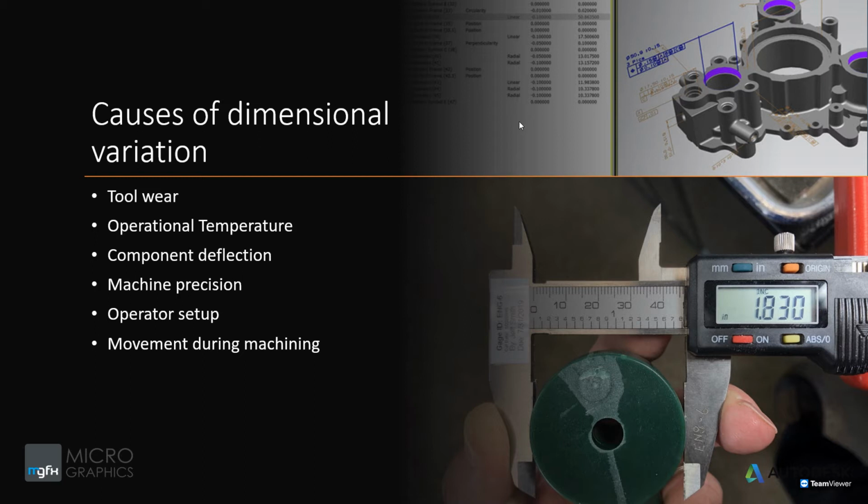Like I just spoke about earlier, we know that different manufacturing processes have various sorts of tolerance values. That depends solely on the nature of how a part is made. So for example, machining might be a little more accurate. You're working with 0.1, 0.005 tolerances, depending on the part and depending what type of method you're using, whether it's a CNC machine or a milling machine, or whether it's a very skilled artisan who's working on a lathe, for example. So those are things that will affect your tolerances or it will give you dimensional variation.